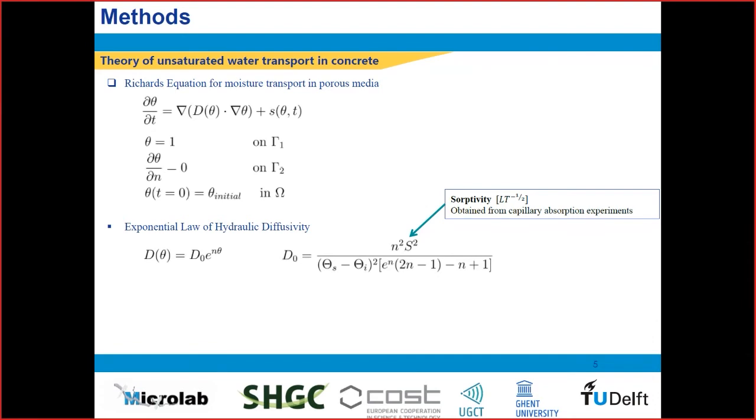Now, if we are rigorous, in order to simulate unsaturated moisture transport in a porous media, we are talking about the two-phase flow in which we have one species, which is the moisture, that we treat through the moisture content or the saturation, and we have the pressure of the non-wetting fluid, which would be air. This entails that we have two partial differential equations, which are tightly coupled, and which is, as Branko mentioned or hinted before, quite more complex than just having one PDE.